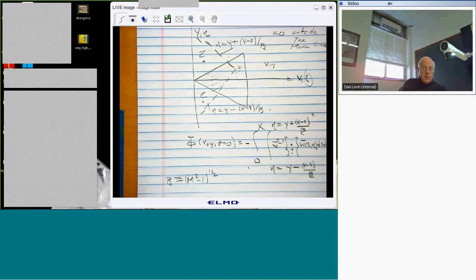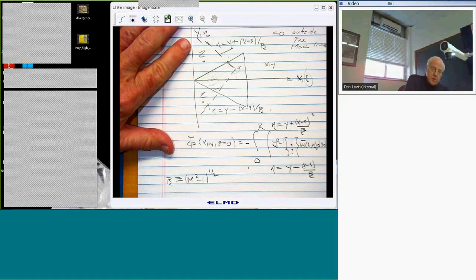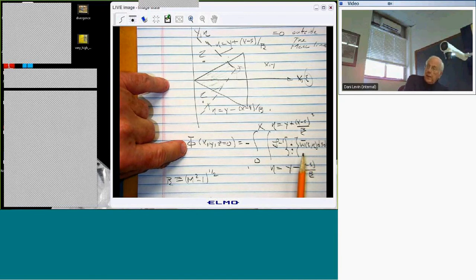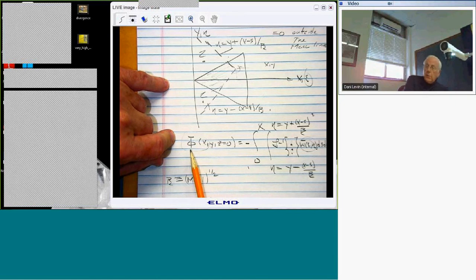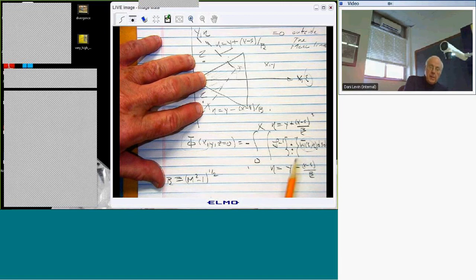So we have one boundary condition off the wing, and we have a different boundary condition on the wing. So if I look at this equation, on the wing, I know this, but I don't know this. Off the wing, I know this, namely it's 0, but I don't know what the effective fluid velocity is, because remember this is really the fluid velocity, which I'm setting equal to the body velocity when I'm on the wing, but when I'm off the wing, I can't do that. So I effectively need to determine this off the wing and this on the wing. Right? But it's okay. I've got an equal number of knowns and unknowns.